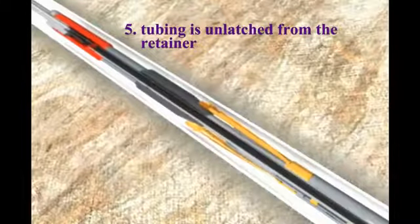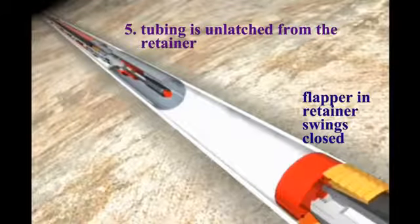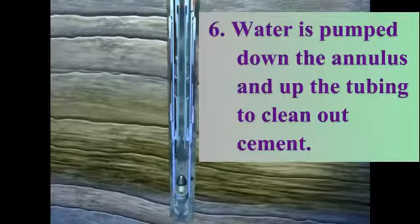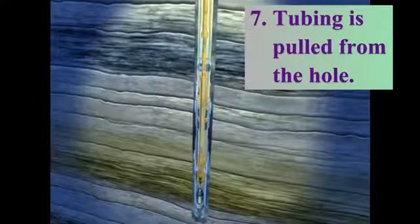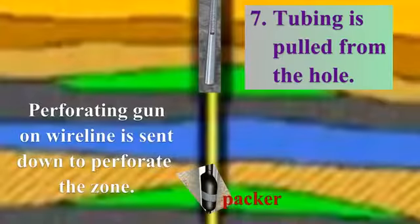After that, the tubing is unlatched from the retainer and a flapper in the retainer swings closed to prevent cement from flowing back up. Then water is pumped down the annulus and up the tubing in what is known as reverse circulation to clean out the cement left in the tubing. After that, the tubing is pulled from the hole and a perforating gun on a wire line is sent down to perforate the upper zone.